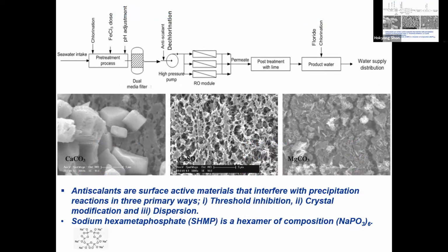So, anti-scalant. If you look at calcium carbonate, you remove the water, desalinate, and then the concentration of salt, calcium bicarbonate or carbonate keeps increasing, and they continuously concentrate on the membrane surface. So calcium carbonate, as you can see, creates scaling and then clogs your membrane.